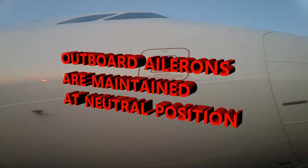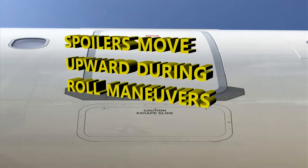Your spoilers, okay, that was ailerons. Now I'm talking about spoilers. Your spoilers 3 to 7 move upward during the roll maneuvers. Remember I said it was like a supplementary. It's augmenting the control of what the ailerons are doing. So roll, right? It's augmenting or supplementing, but it's helping with controlling even further the roll from left to right of the aircraft.